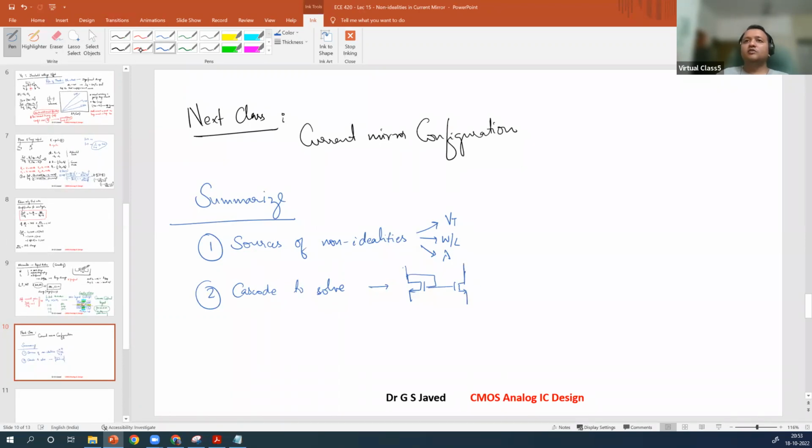So what this will do, you will introduce a VGS term and ensure that these two terminals, X and Y, their voltages will become Vx equal to Vy, and these two voltages, Vp and Vn, will be maintained similar to the below cascode.